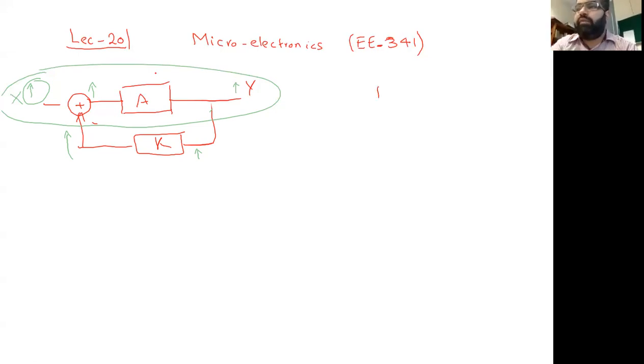But the main thing that I would like to reiterate is, if you have, for example, input here and output here, V in and V out, and V in increases, what will happen with the V out? We can see this in multiple ways. This is a common source amplifier, right? If I ground here and V in increases, since common source is inverting, in any case I can say the V out will go down. That's one way of seeing it.